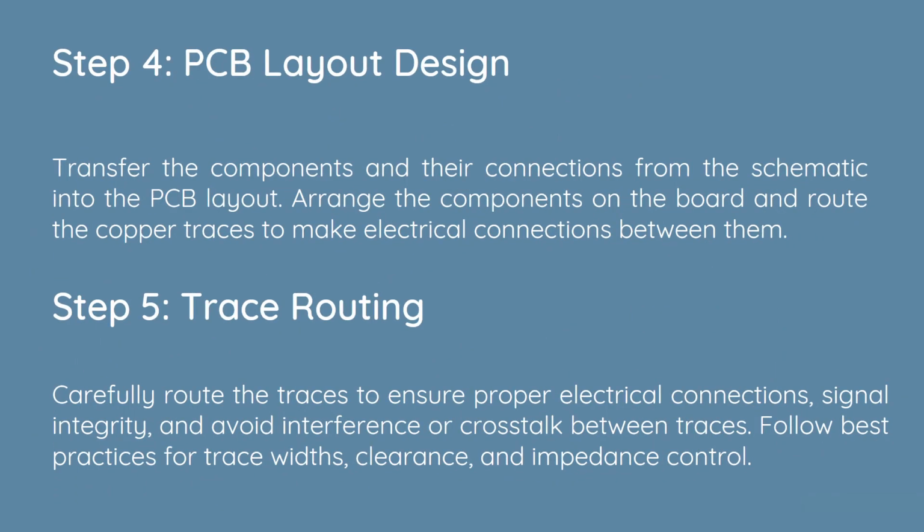Step 4. PCB layout design. Transfer the components and their connections from the schematic into the PCB layout. Arrange the components on the board and route the copper traces to make electrical connections between them.